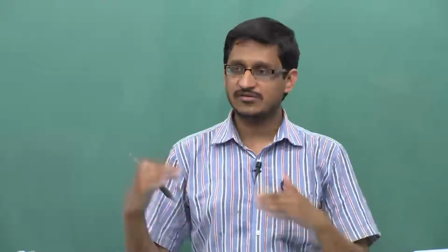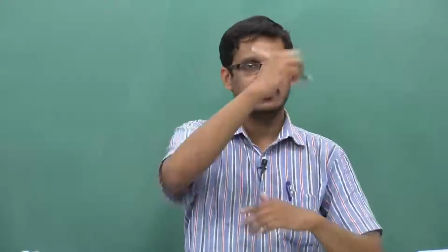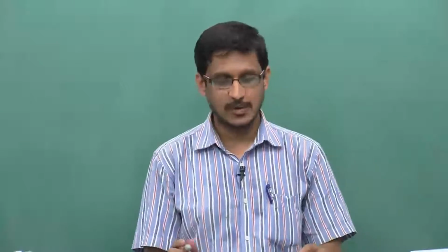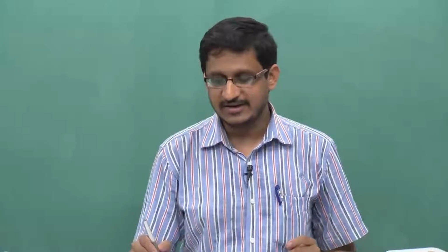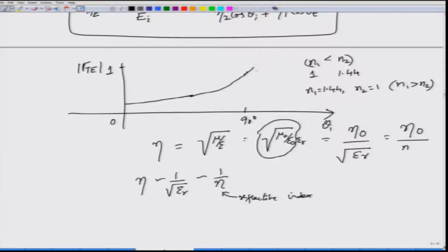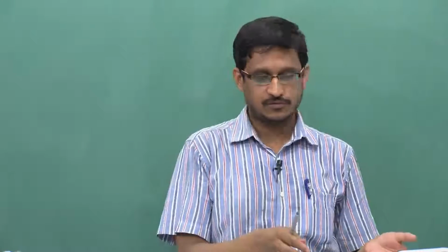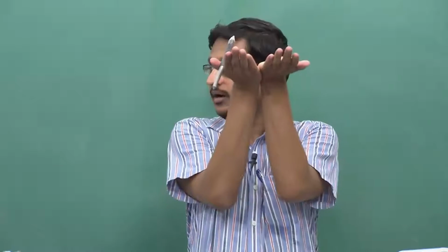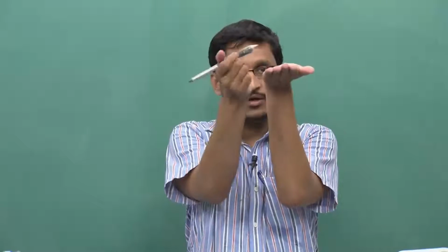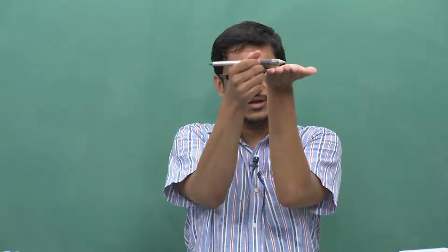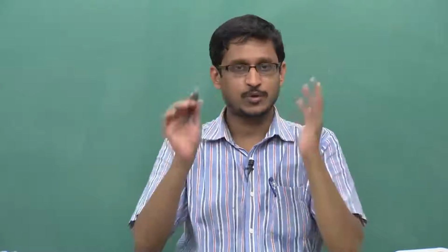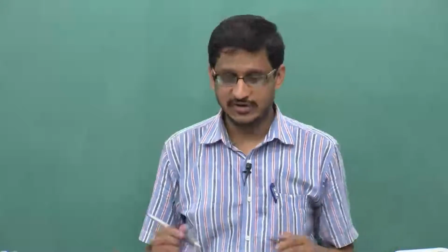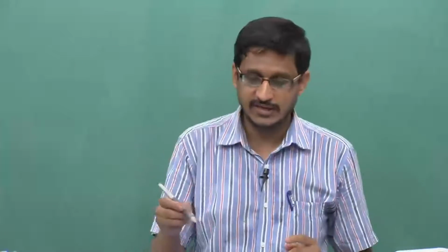Okay. This is called grazing angle incidence and transmission from the grazing angle, and this is valid for both TE as well as TM waves. So that is why at 90 degrees the reflection coefficient goes to 1, that is, almost the entire wave gets reflected. You can try this. If you were to take a book and hold it up and try to read, you will get maximum reflection because light is getting reflected. If there is anything printed on the piece of paper, you will not be able to read it. So this grazing angle is something that is common to TE and TM.